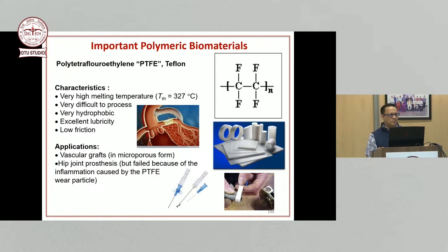PTFE, or polytetrafluoroethylene: very high melting temperature, difficult to process, very hydrophobic, excellent lubricity and low friction, used for vascular grafts.